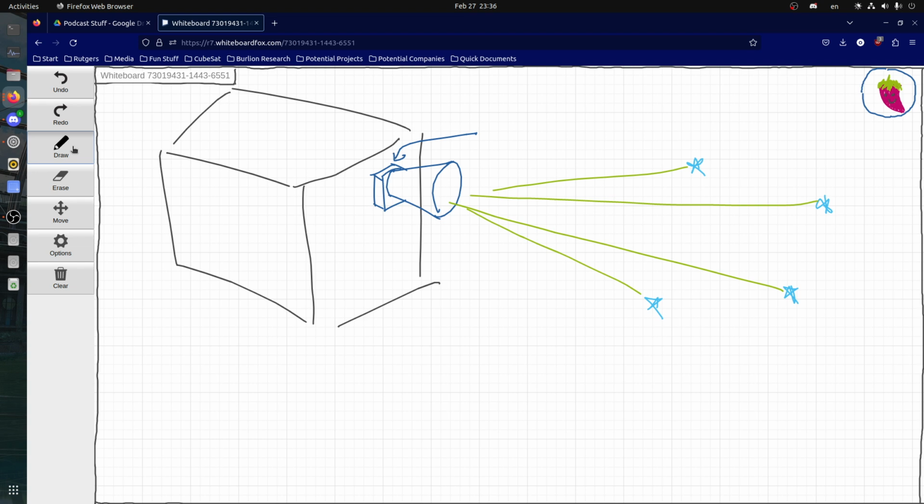And I think for most star trackers, it's a norm where you can do dead reckoning. So if you turn on the star tracker, it's usually less than 10 seconds to figure out exactly where you're pointing. Because once it knows where it is, it's not really a matter of finding itself from scratch. It's more like, I'm just gonna make little updates, like I already know I'm pointing in this direction. I tilt a few degrees. I just need to search in that general area of the night sky.